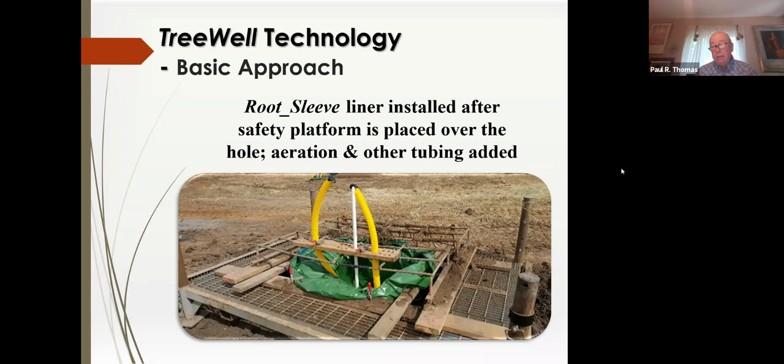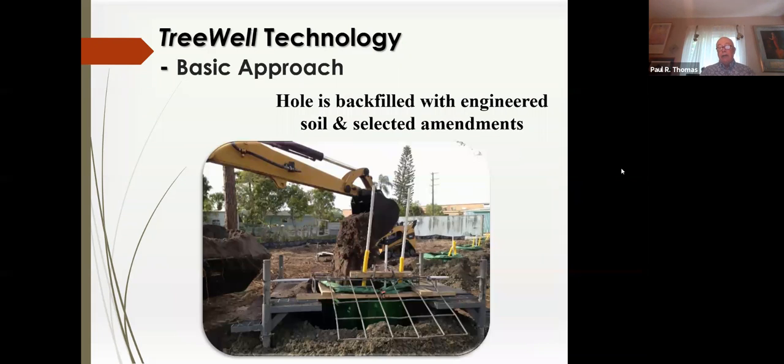Once the hole's completed, we have a steel platform that has this liner loaded onto it, that is placed over the hole by a skid steer with forks, and our goal being to keep people from going into the hole. That's our primary goal on all of these projects. So once that's placed over the hole, then the liner gets dropped.